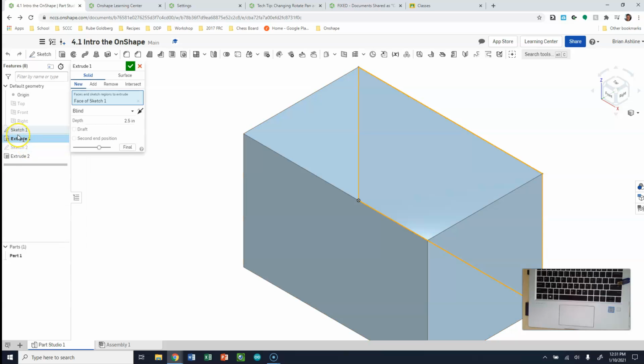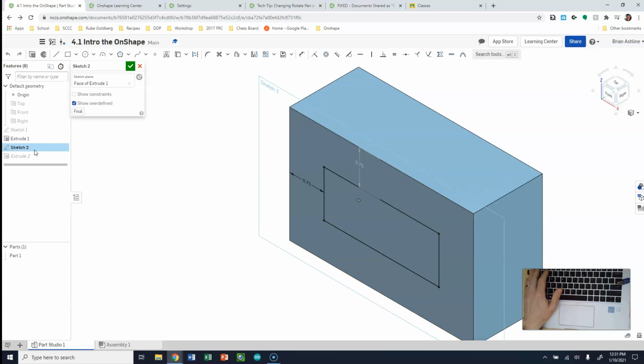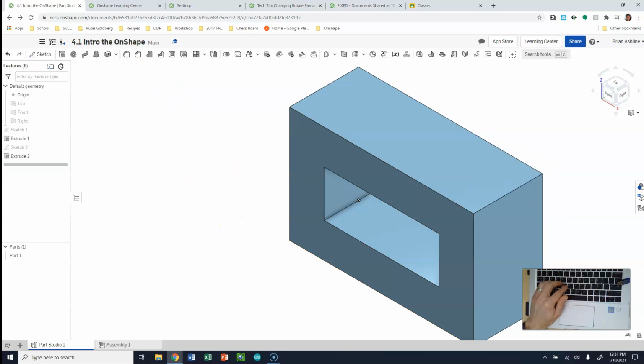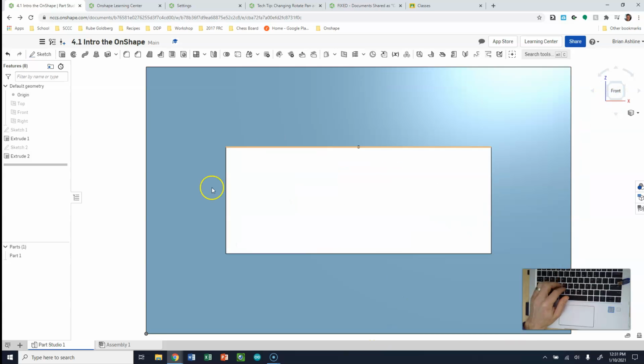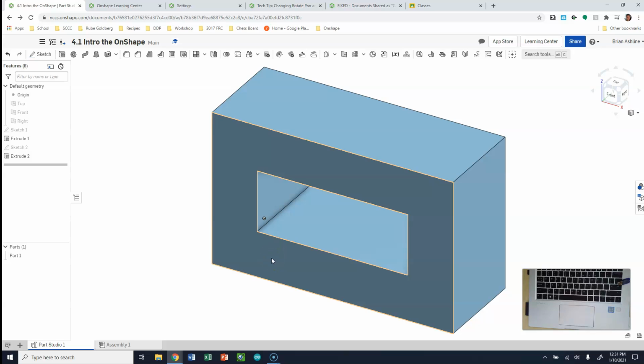And edit things like extrusions and change them back to 1.5 inches or whatever we want to be able to edit. We can change, again, sketches and edit how that works. Or again, we can change extrusion so that it's done right. Okay? So either way, those are the things that we've really discussed today.